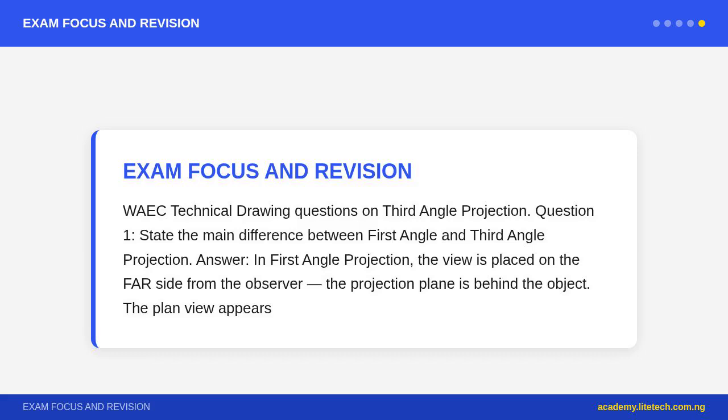Question 5. Why is it important to state, using a symbol, which projection method was used on a technical drawing? Answer. Technical drawings are used internationally. A drawing made in Nigeria may be manufactured in Germany, China, or the USA. First angle places views in opposite positions to third angle.